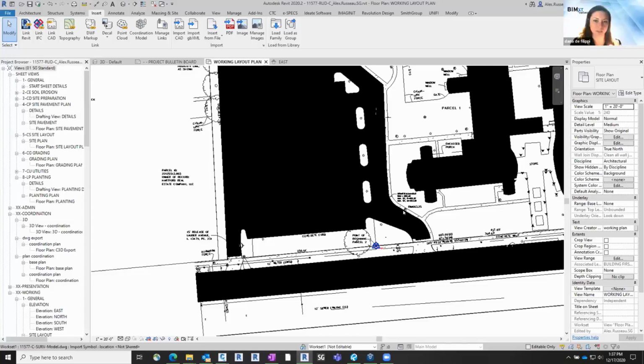And just to be clear, what you're setting up now would be kind of what Nick was referencing before, that site specific Revit file that everybody's going to link to. And really, depending on what you're trying to do, you can actually set the shared coordinates up before you bring the Civil 3D file in.